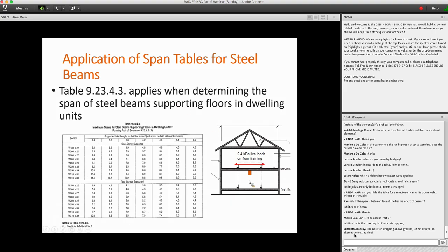And so I've drawn here on the bottom right an orange box, which is just representative of the location of an I-beam that may be supporting a single floor. If there was a wall that was above that I-beam, continuous up to the roof, then it would be supporting 2 stories potentially, or if that I-beam was actually down in the basement, it would be supporting potentially 2 stories. So the table is set up to allow for up to 2 stories support. And if you read carefully, and that's the trick with all of these tables, there are so many assumptions built into them to make them work.